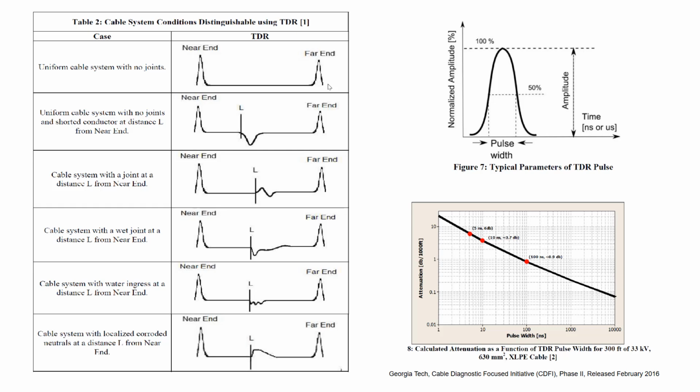Note that this oscilloscope is at the near end only. As you can see, in the first slide we have shown the block diagram of this injection method. So the oscilloscope is kept at the near end only. The oscilloscope records the near end signal, and then after some time t, it will record the far end signal like this. So what kind of fault is this? This is an open circuit. The cable is open at the other end. So you see no reflections in between, no changes in the waveform in between. Only the near end and far end signals are clearly seen.